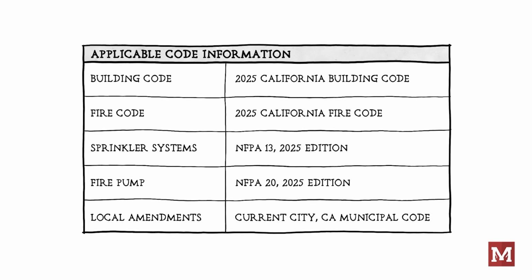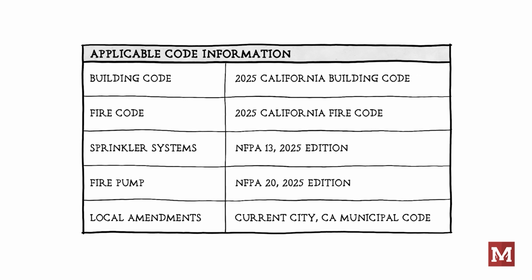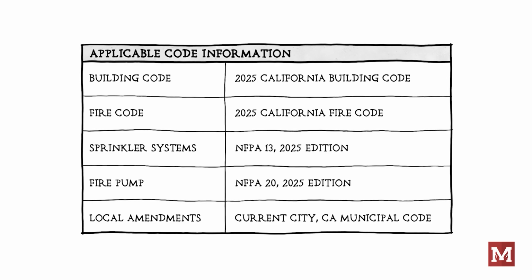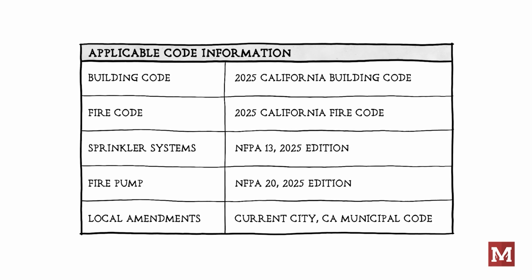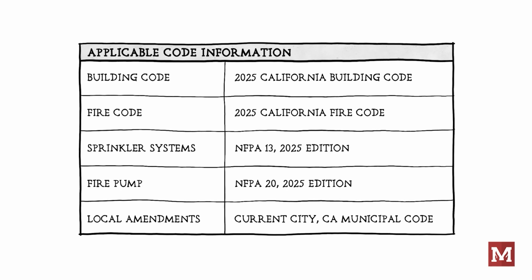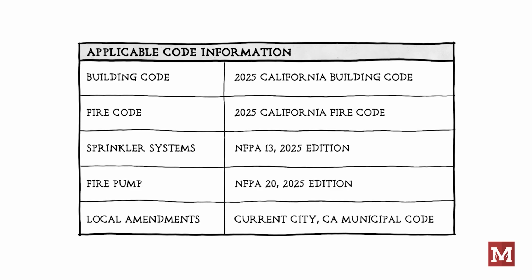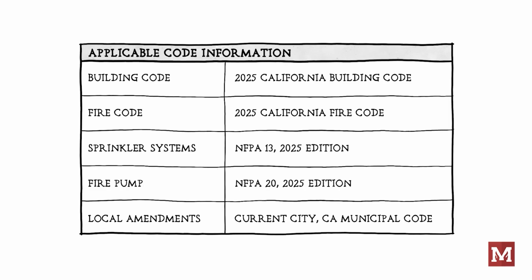In my case, for example, over the last year, we've submitted automatic sprinkler plans to 15 to 20 AHJs. In those, the governing revision cycle for those projects has been as old as 2013 NFPA 13, all the way through 2025 NFPA 13. My designers need to know which edition of 13 they're working under, and this is where they should be able to find it.